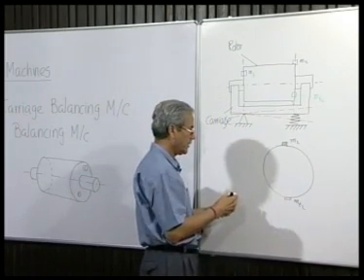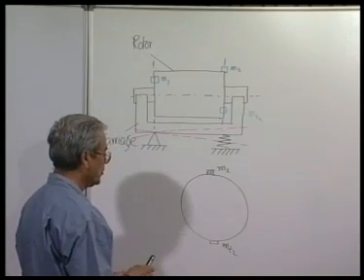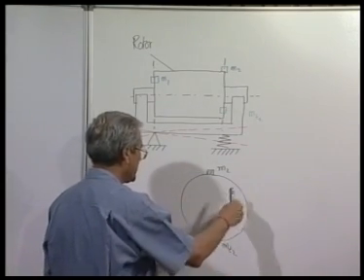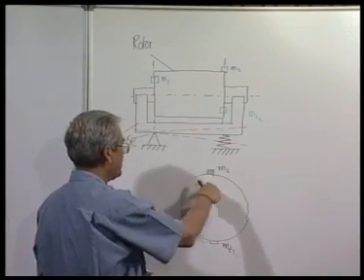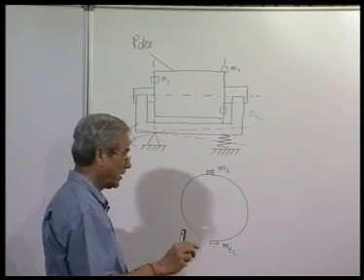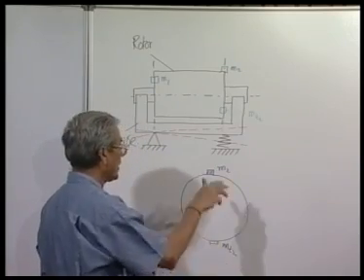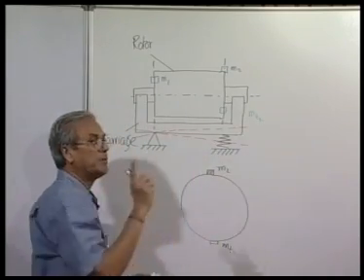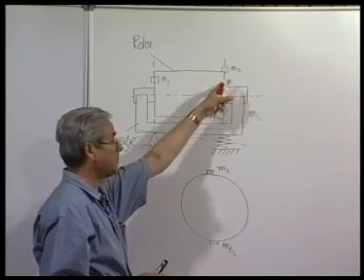diametrically opposite. At any other position, the amount of m2's inertia force which this will neutralize will be lesser. Here it will have maximum effect. Therefore, the amplitude of oscillation will be minimum due to the unbalance created by m2.